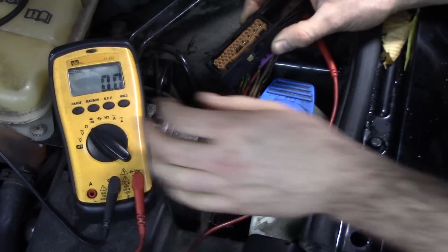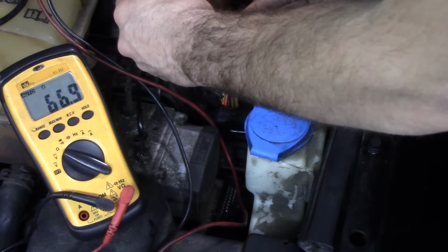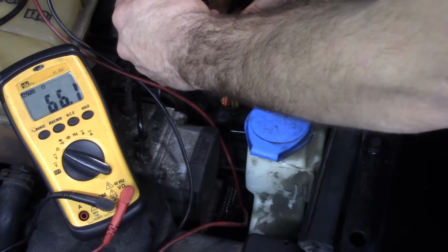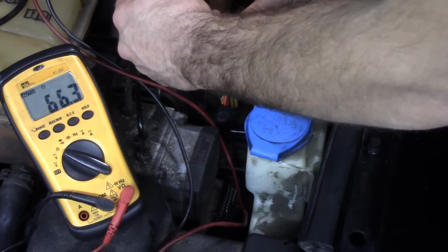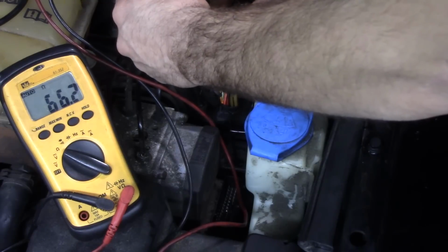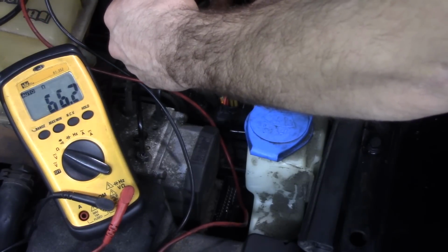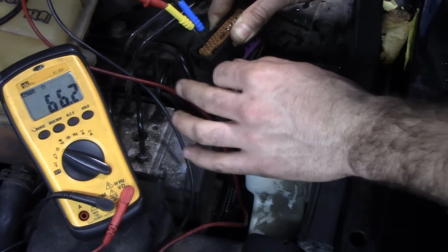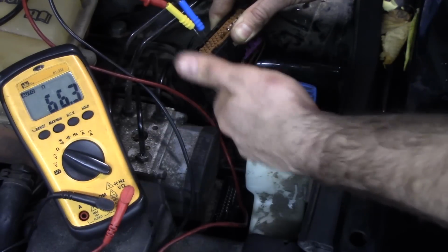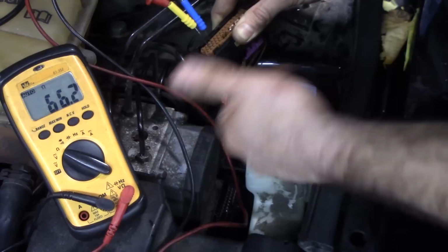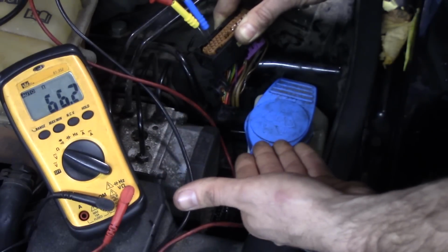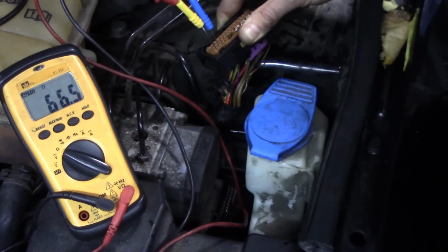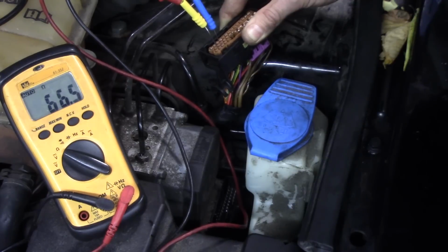So we're just going to switch this to ohms. Alright, so I just switched the meter on ohms. I'm connected to these CAN lines. This is looking at the network. Our spec was 60 to 72 ohms. We have 66.2. And I have to hold these pins there, but these pins are just sitting in here. They're not stuffed in there spreading any terminals. So from our ABS module out to the network is good, and what this needs is an ABS module, and I think that you can get these separately. So that's pretty much it for this one.